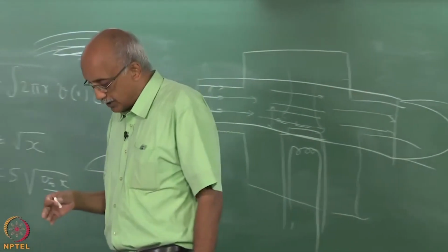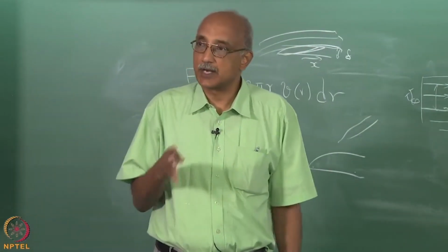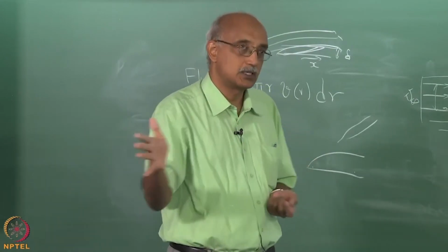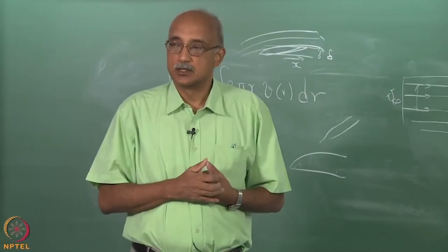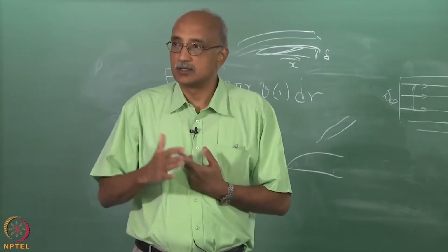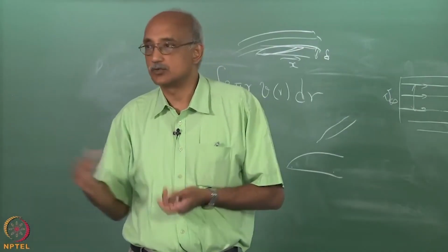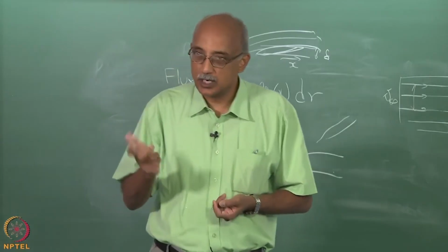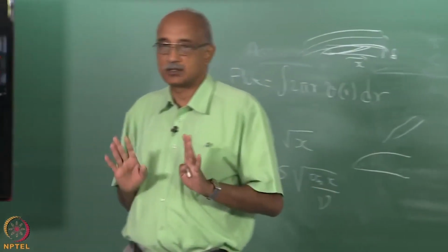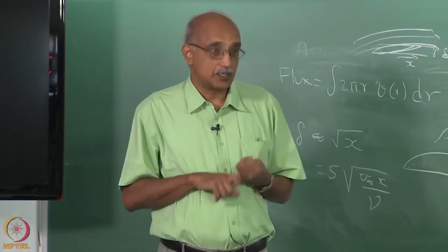So, that is another argument for keeping the Reynolds number as small as possible, so that this transition will happen faster. As you can imagine, as the flow velocities increase and the Reynolds number increases, the likelihood of never having the transition take place is higher. I mean, the fluid could just go past the plate in plug flow and then exit before you know what is happening. So, by slowing down the flow, a lot of good things happen. That is why in a CVD reactor, the whole intent is to keep the flow rate as low as possible. It helps us with managing the flow dynamics.